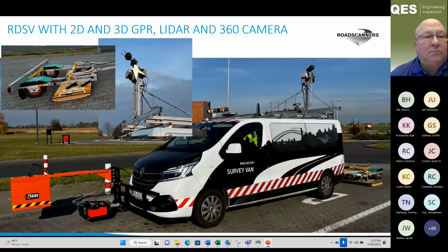Okay, then this slide is, and next thing what I'm telling you, probably not all of you like too much, but over the last 5 years, we've been doing extensive testing with the 3D radar, ground coupled and air coupled antennas, and based on this test, we have ended up recommending and started to use ground coupled antenna.